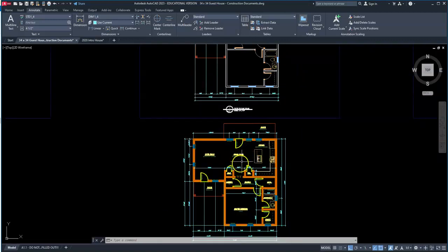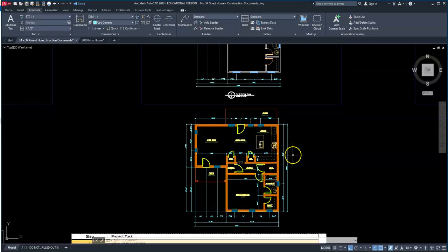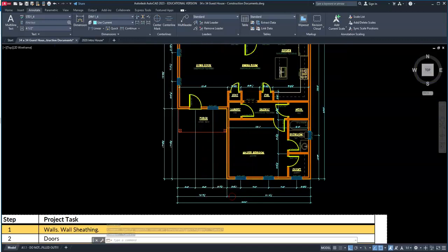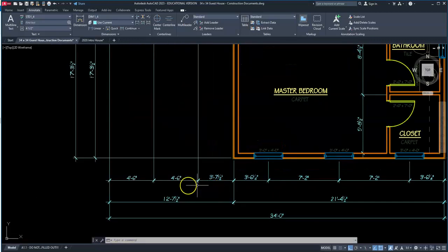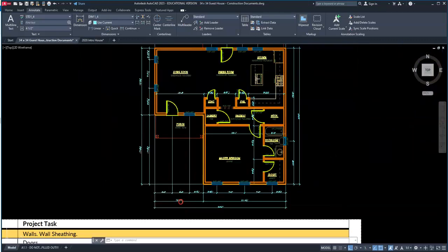You may have a question that you only see 2 lines of dimensions. That's okay because we only have 1 wall. If we had 2 sets of walls, one here, then we would have this second line of dimensions, and then the overall. Here we just have our window and then the overall. Completely fine. We just want to make sure that we have a defined boundary. So if we have these 3 dimensions, we total them up and they equal this. That's why we do that. It's quick for the estimator, and it's quick for the framers in the field.